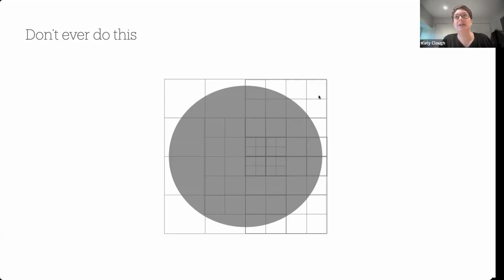So if it happens that your 16 by 16 box ends at this boundary, just because it's refining all over here already, then sometimes these edge cells will just not get refined. You have to force it to over-tick where it wants to refine. You can add buffers to where you designate for refinement, to push the boundaries out further and make sure it refines the whole thing you're interested in and doesn't cut off a corner.